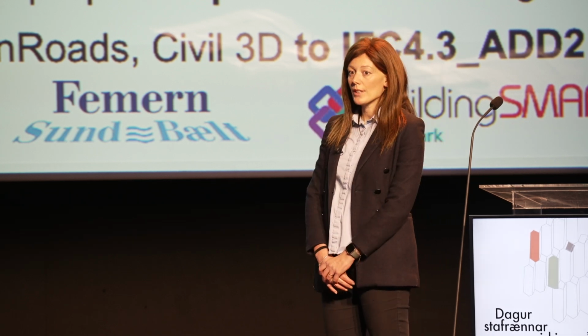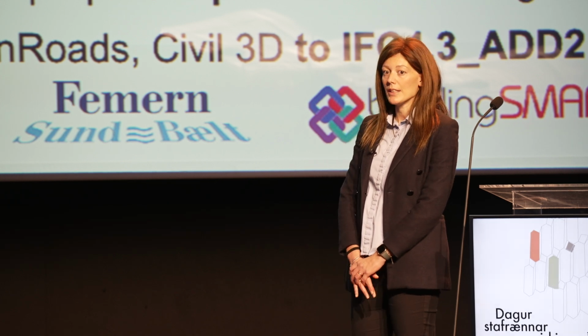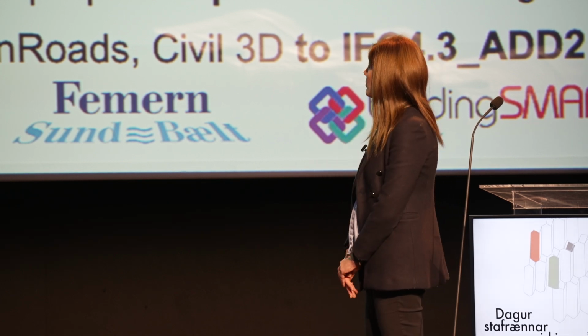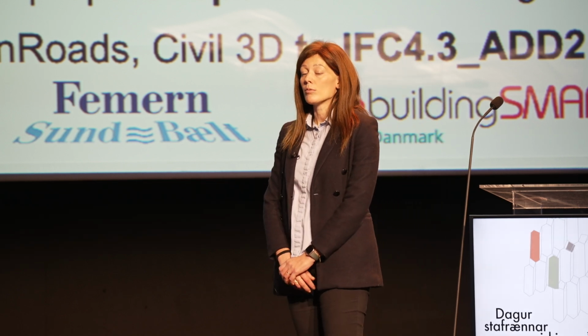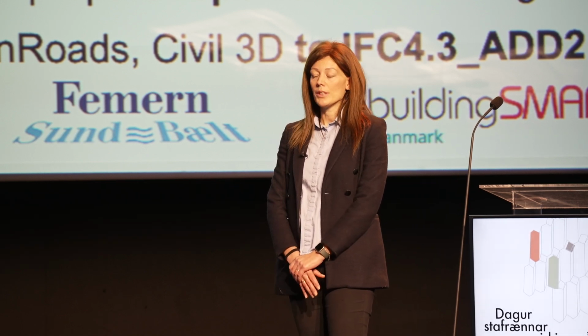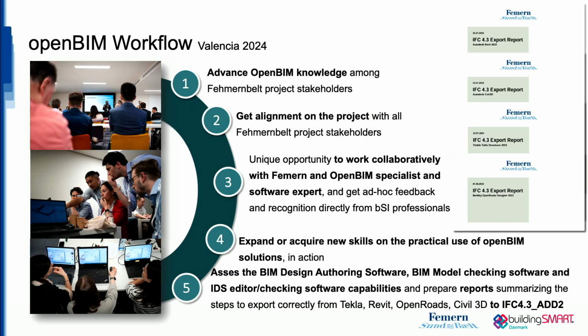So the first main takeaway after the workshop was to issue this IFC 4.3 export guide, made thanks to the support of the BIM authoring software experts, to give to our contractor to help them step by step in the export to IFC 4.3 according to our exchange information requirements and on how the properties should look in the model.